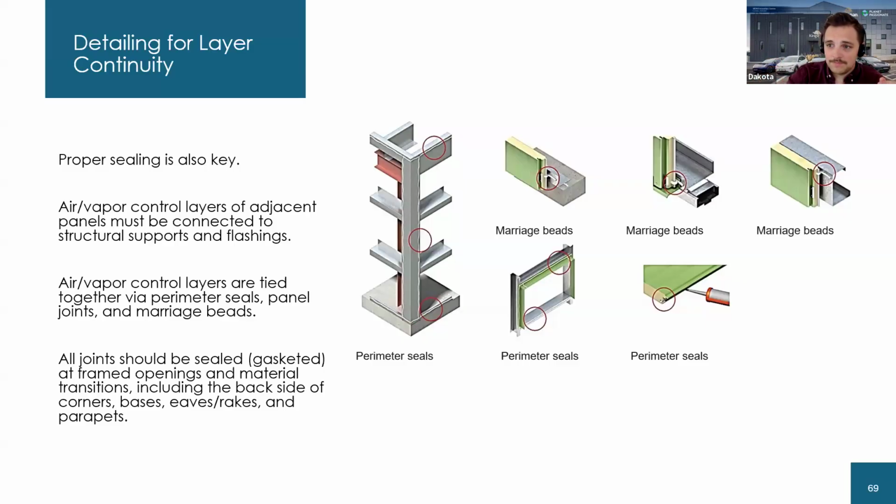We do two lines of that. And you'll see at all the really important points we need to see that caulking occur. We're going over back gaskets to keep the system from being compromised laterally. We're going on the back side of the panels where it's making contact with that structure, again, being really redundant to make sure that everything is locked tight and going to be lasting the test of time.